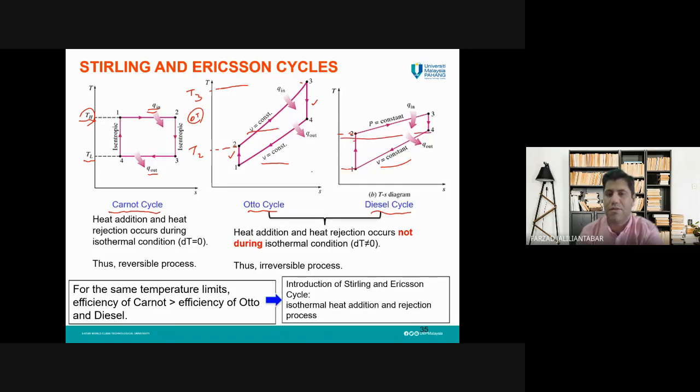It is a constant volume process. And also for the process from state 2 to state 3, which is the constant pressure heat addition process, we have that delta T. And if you remember from thermodynamics, one type of irreversibility is the heat loss due to this temperature difference.